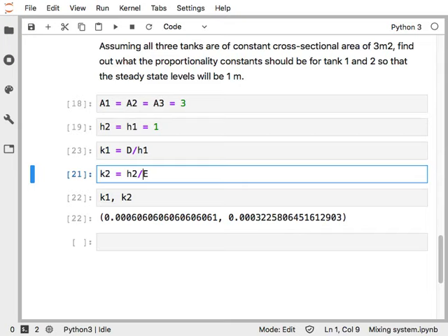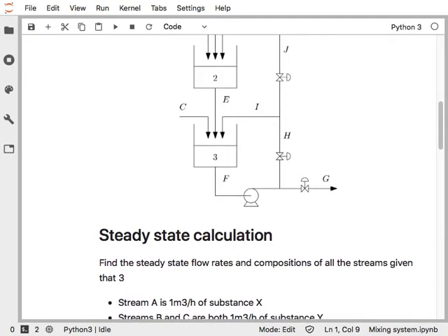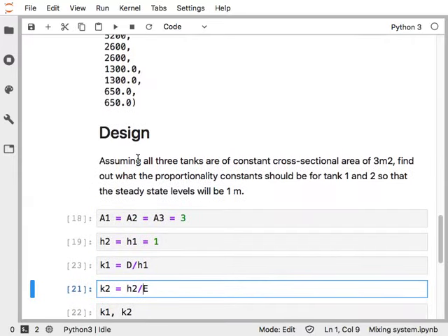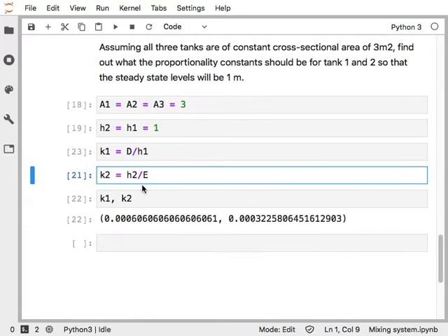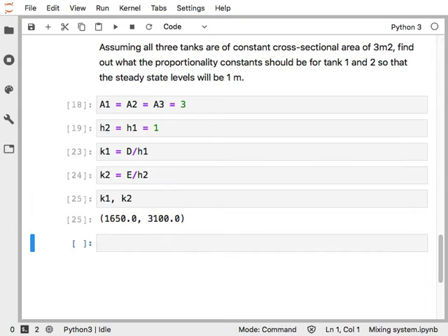Now notice here, I looked at that and was like, that doesn't look like what I'm expecting when I'm thinking about a flow. All these other flows are in the thousands, right? So why am I not seeing a flow constant in the thousands? And again, this is why I highly encourage you to check your results at these kind of intervals. Okay, that looks a lot more reasonable. That's in the thousands as I expected it to be. So now I know that I've solved that problem correctly.